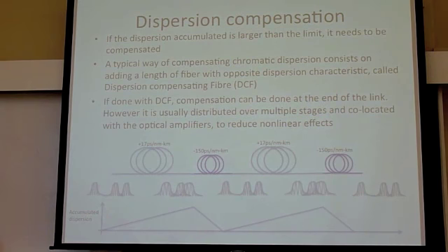Okay? If I do direct detection, I just check the power there. What happens is that I lose total information about the phase of the signal, so I cannot do anything about the phase compensation. So there are some electronic compensations which work on direct detection, but there's only so much they can do.